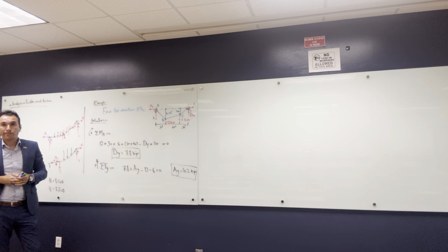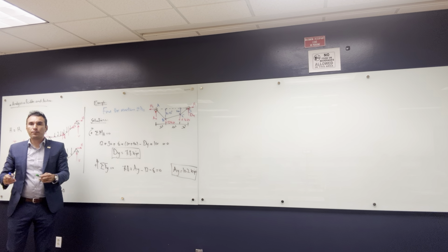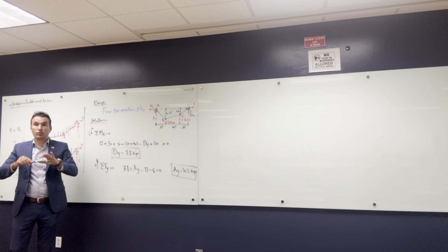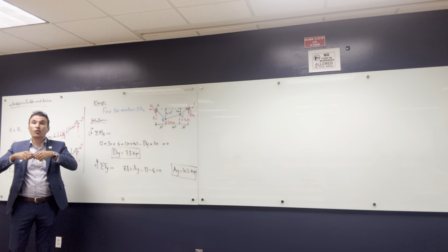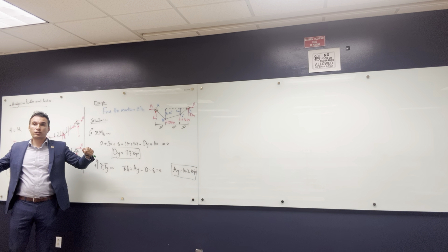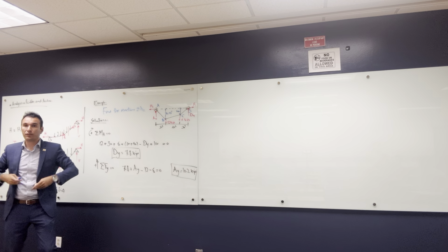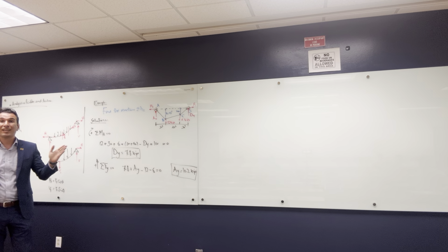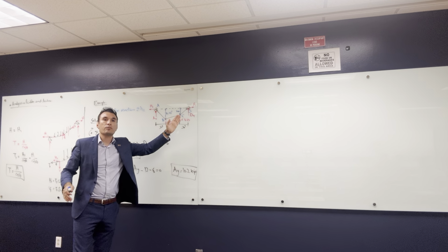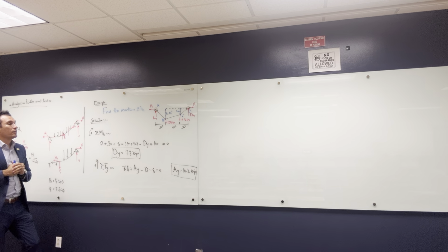Professor, sorry, again, why is the moment zero on the left or the right side of the cable? Because last time when we were discussing, a cable is not like a solid cross section. A solid cross section resists moment, but a cable is a flexible member. Correct. So it allows no moment at all the points on the cross section. Okay, so it only takes tension. Correct. It doesn't have bending moment. It can't take compression. If you make a cable and try to compress it, no. So the moment at the cable, either from the left or the right, so all the points at the cable can be treated as an intermediate hinge. You can take the moment left or right equal to zero. That's one property about the cables.